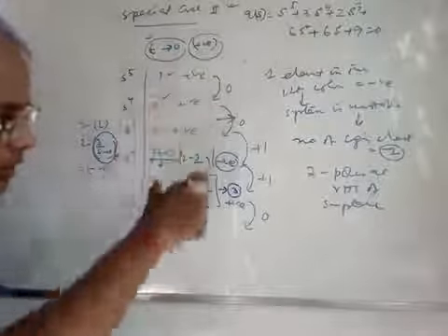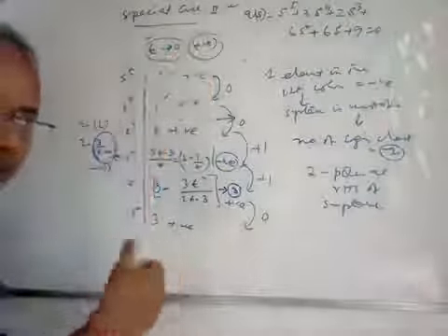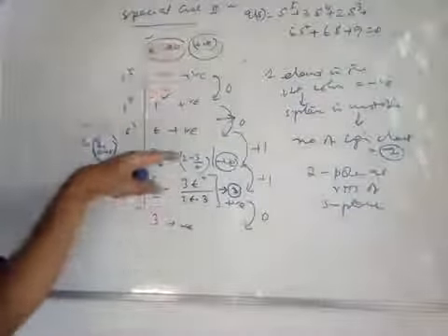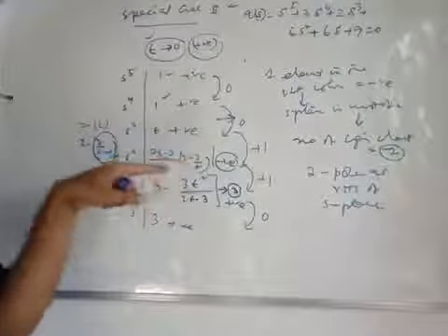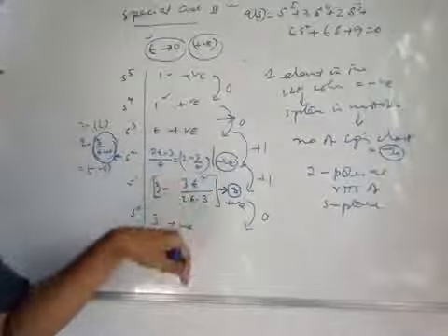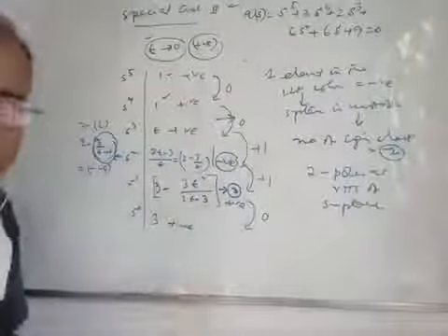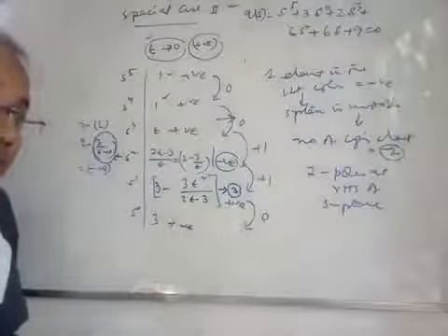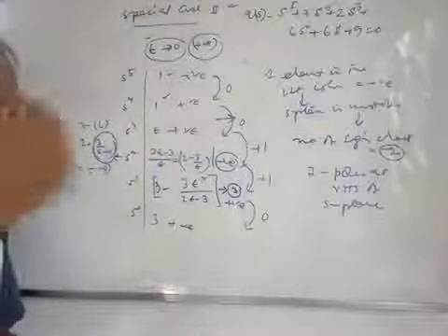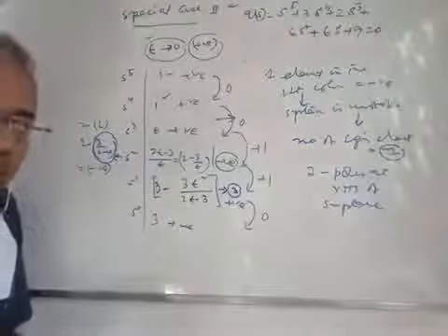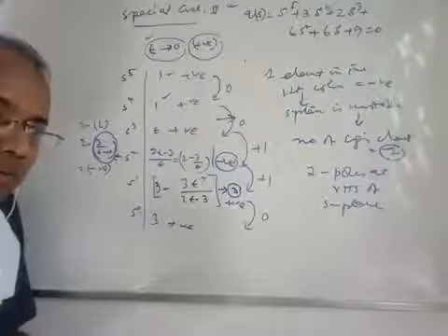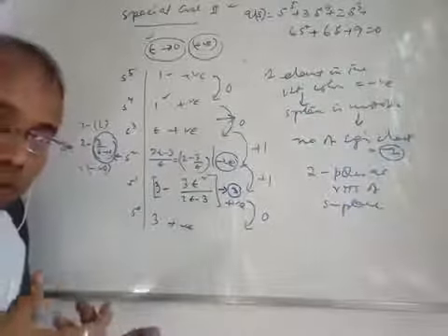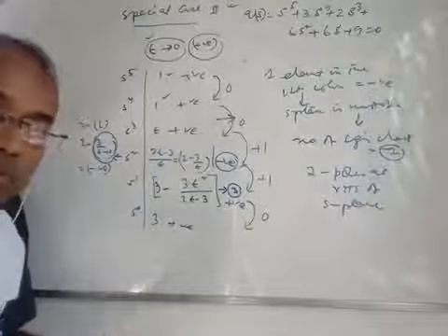Based upon that, you construct the complete Routh array, and from that you find out which elements at the limiting case of epsilon tending to 0 are positive or negative, and the rest of the things are the same. Okay, so this is the way the special cases of the Routh array formulation are worked out, and different kinds of problems can be solved.